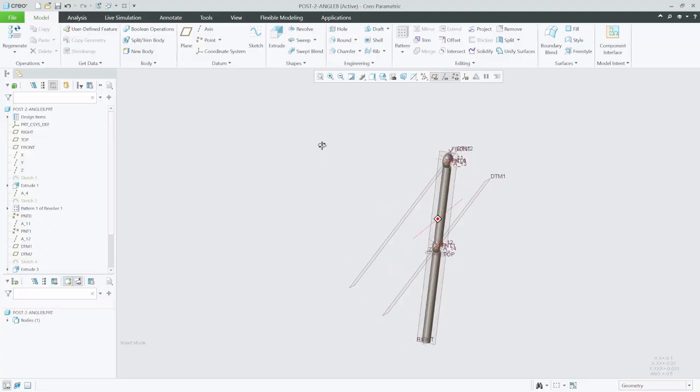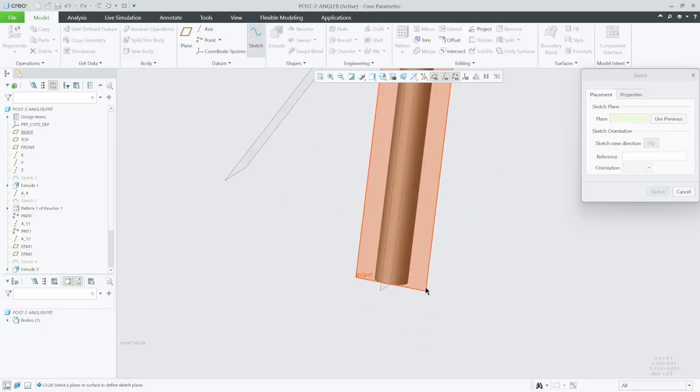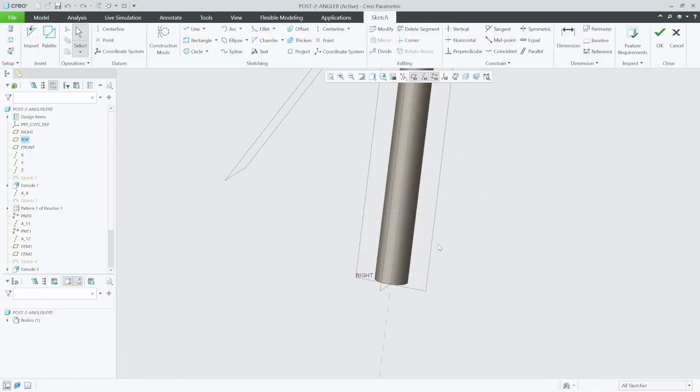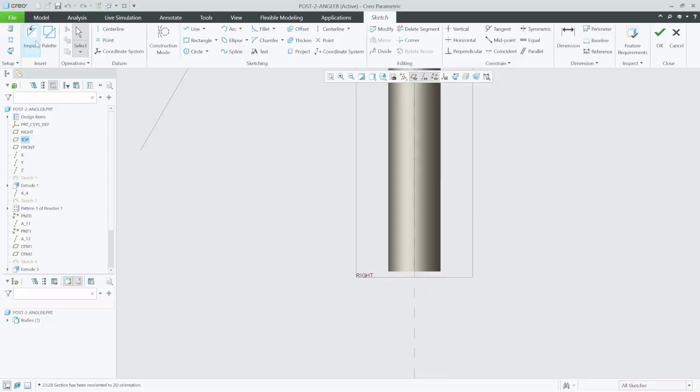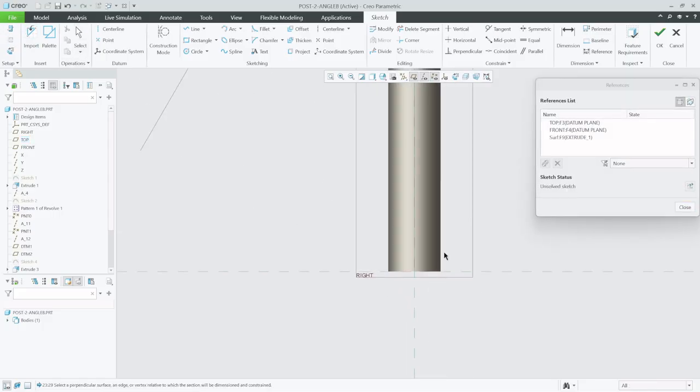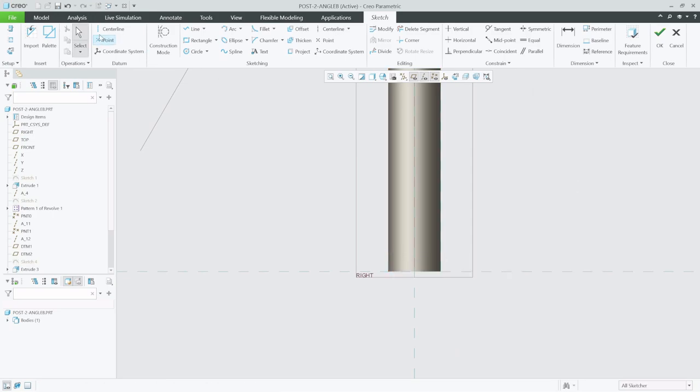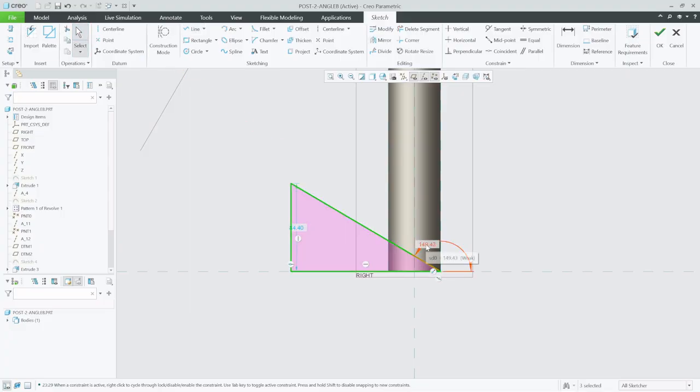Those two now. Okay, and then one more thing we just need to add here is a sketch view. We need to go references here, reference, say close, say sketch line, say there, there, select 150, so we get a 30-degree angle.